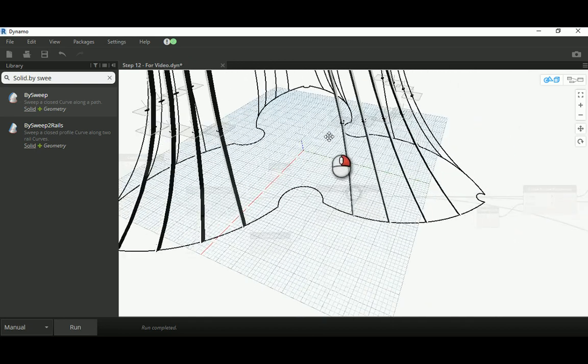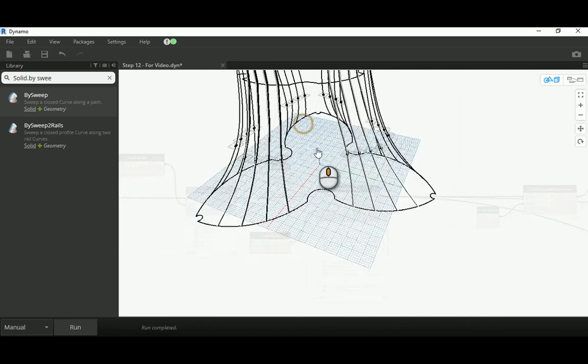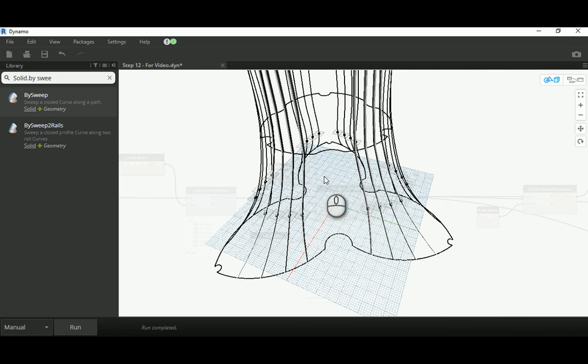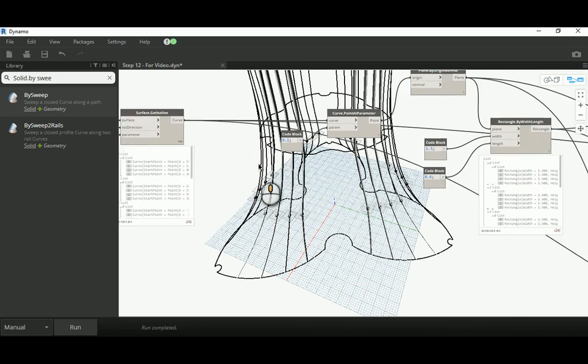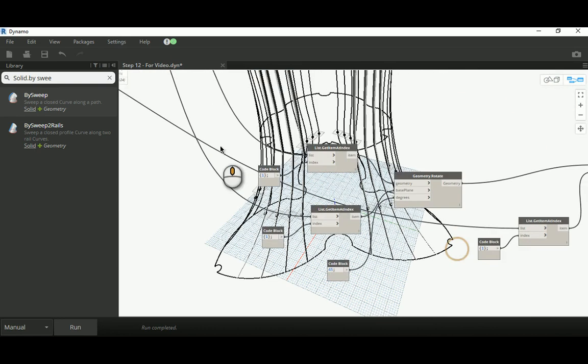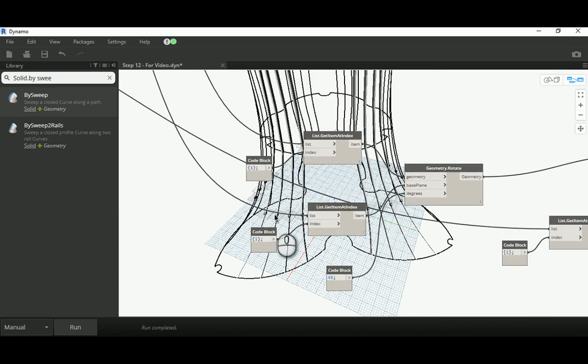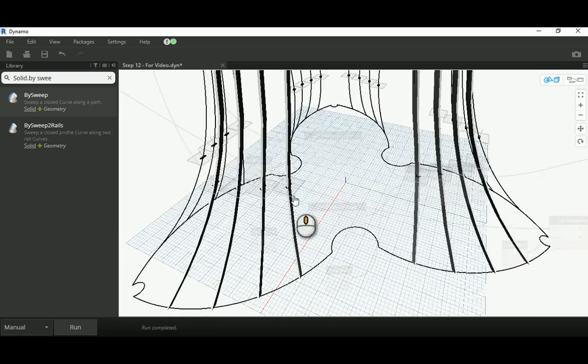Anyway, I will leave you guys to do the rest. Just a tip, that I've done 0 and 1. Number 2 will need to be, I think, minus 50. Number 3 should be 0. Number 4 should be 90. Number 5 should be 90 or minus 90, not really quite sure, to get the overall vertical louvers.